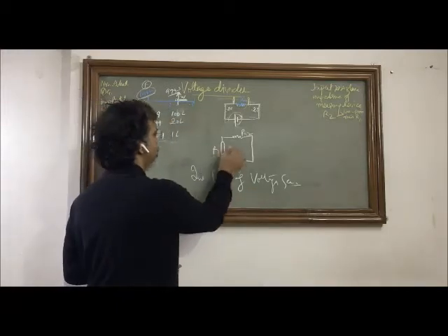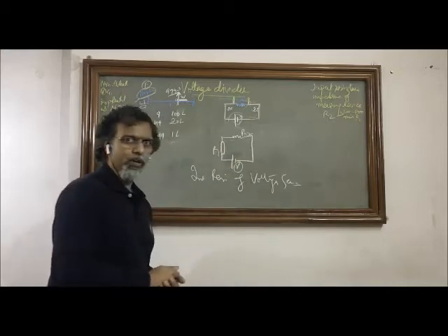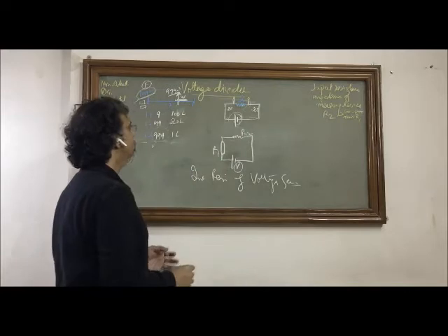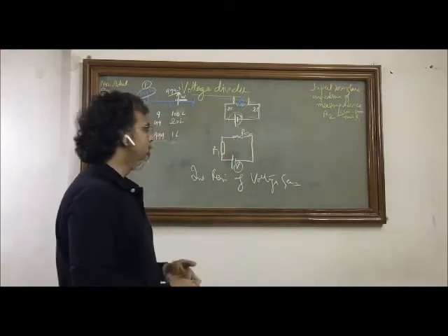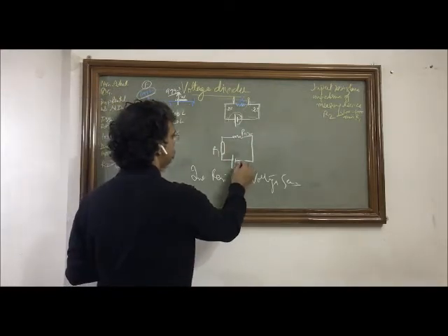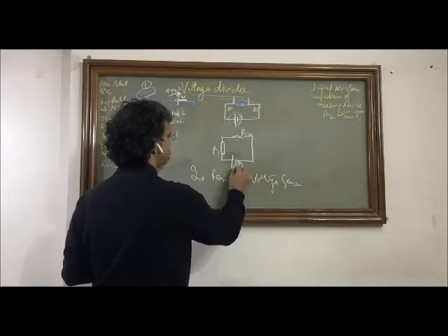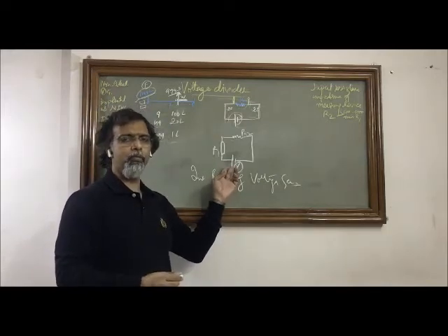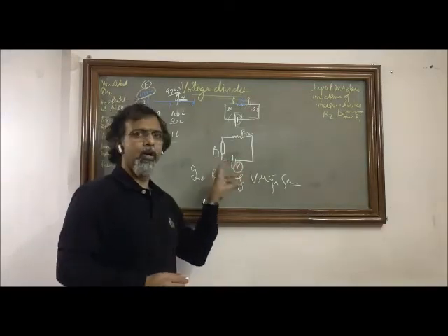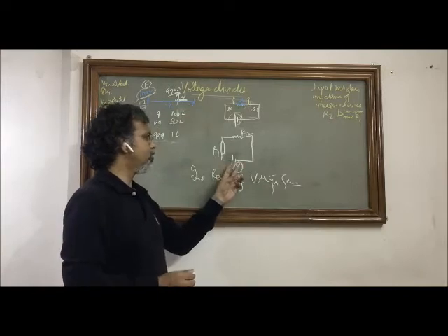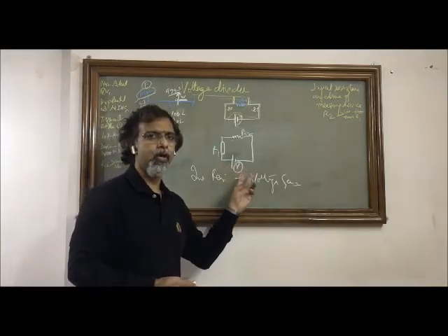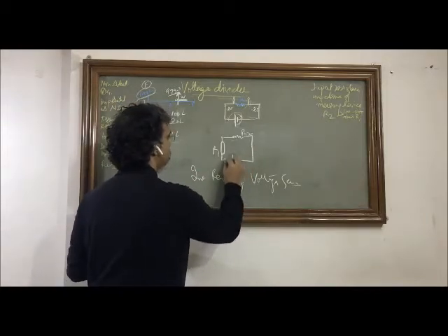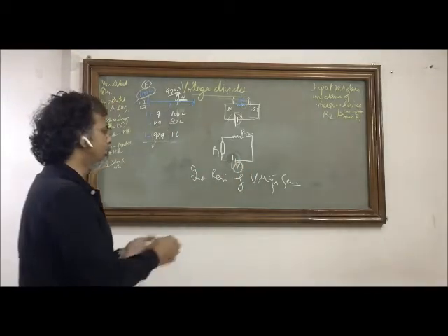So this is a non-ideal voltage generator with R1 as its internal resistance, and now it is connected to an external resistance, R2. With this analogy, assume that we do not know the voltage, or potential difference, across this source. This source can be a battery, any biopotential, a muscle, or skin. It is a source which has some potential difference across its two ends, and we want to find that potential difference.